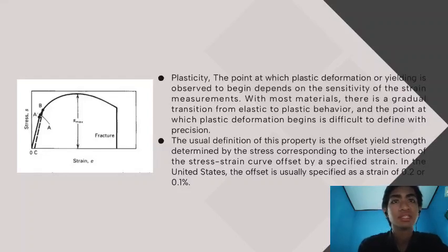the elastic limit is greater than the proportional limit. Determination of the elastic limit requires a tedious incremental loading-unloading test procedure. The critical stress for onset of permanent deformation is difficult to determine precisely because the elastic limit is so low in most metals. It also varies among testing devices and is sensitive to machine stiffness.